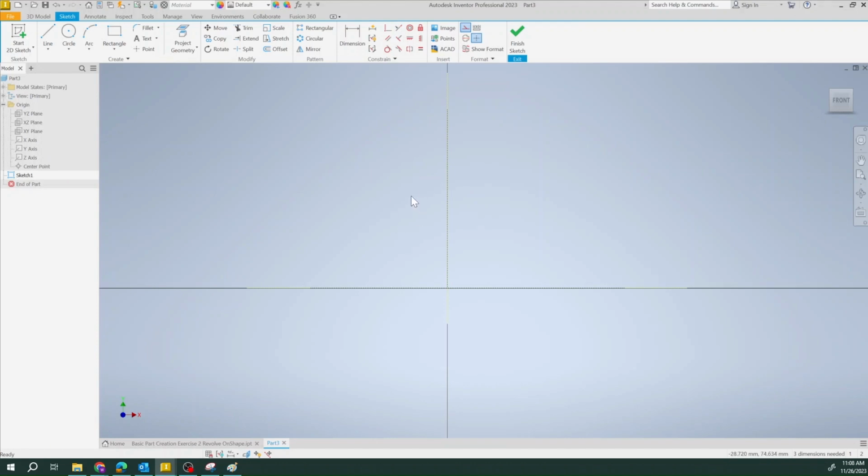So from here, I need to make that other drawing. So I'm going to click the line tool again. I'm going to toggle off my construction lines. And then I'm going to click here along this y-axis along my construction line, and I'm going to just draw that profile really quickly, trying to keep my lines horizontal and vertical as I draw. And then when I come back to the bottom, I want to make sure that I don't actually draw my line collinear with my x-axis, with my construction line. So now that I have this profile, I can now mirror that profile as per the directions.